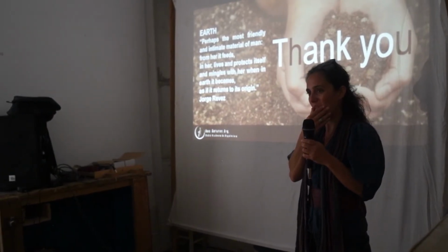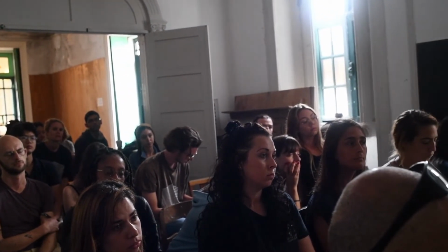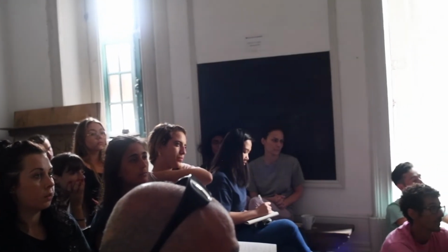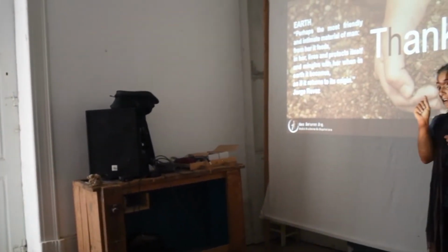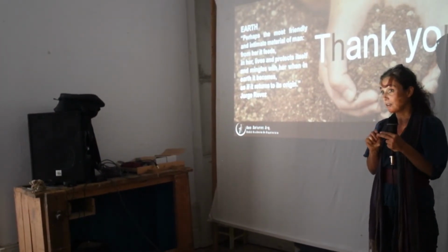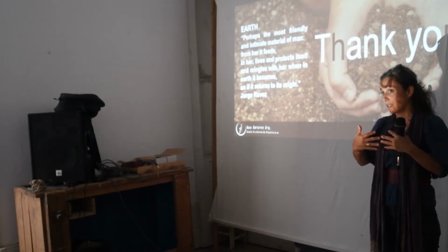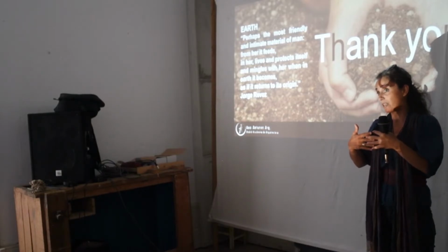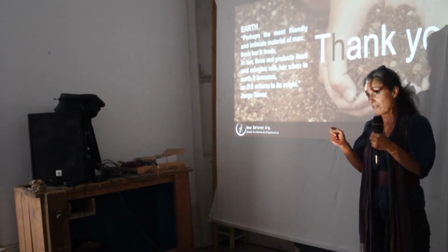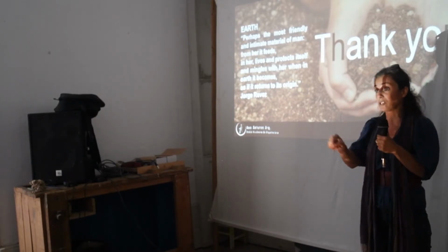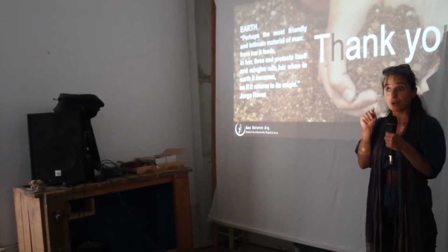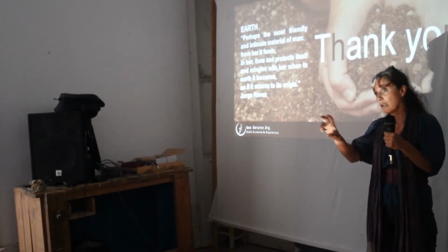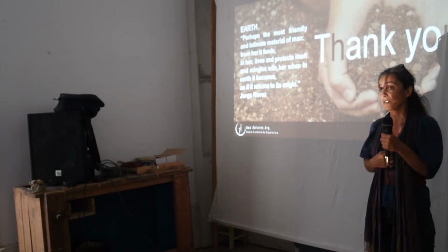And why not use lime instead of cement in this mix? Yeah, you can use lime. The problem with lime is lime needs water, and when we work with compressed earth blocks, the amount of water that you need is very little. So it's difficult to come to a good mix that makes the lime work well and perform well with this kind of construction. But it's possible, and we are able to make very good blocks, better or equal to the ones that you are able to do with concrete or cement.